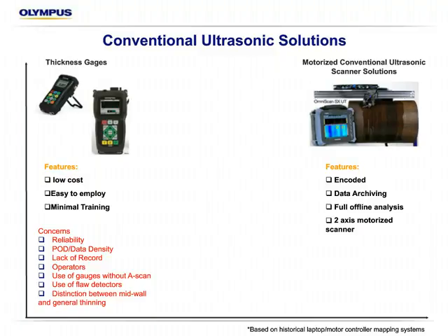Within limits, it's not something you can't do, but today's high-quality thickness gauges do have a lot of algorithms, special features, and measuring modes that will give you the best results in actually getting a thickness measurement versus most flaw detectors. In the last couple of years, a few of the flaw detectors have some options that make them closer to the quality of a thickness gauge for thickness readings, but not quite as good as the best of the dedicated thickness gauges. So the real big hard call there, as I mentioned before, is that if you don't have that waveform, it's really hard to make a distinction between a mid-wall defect versus general thinning or some other type of condition.